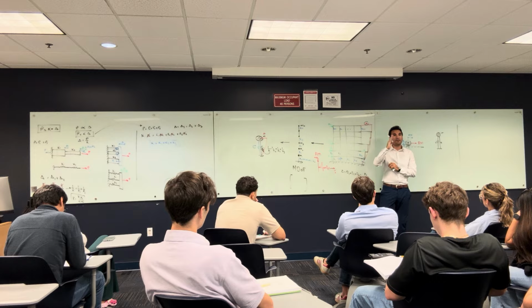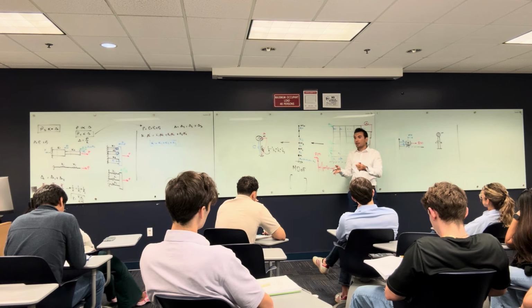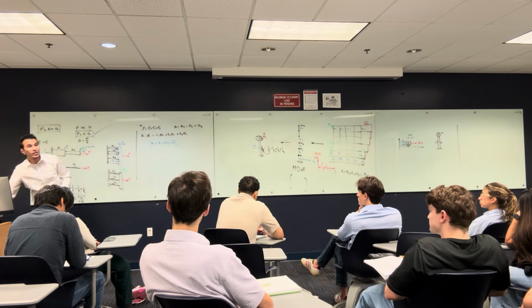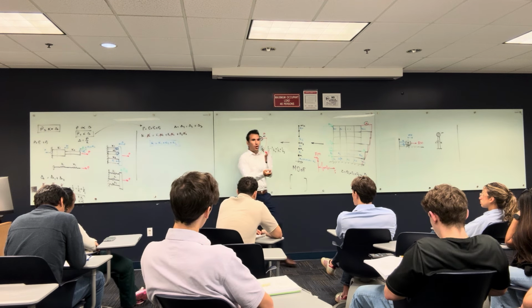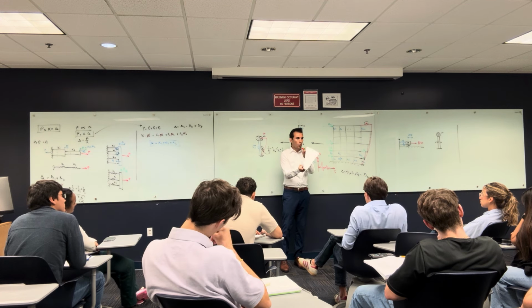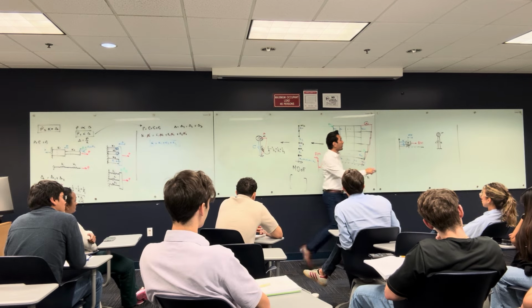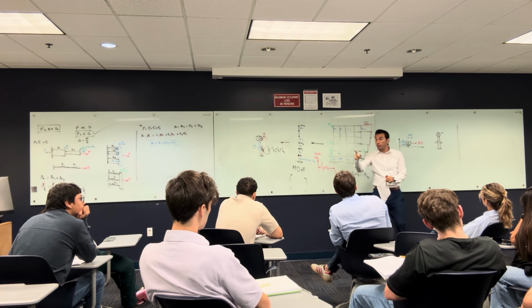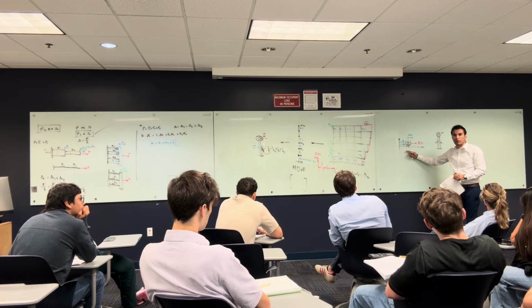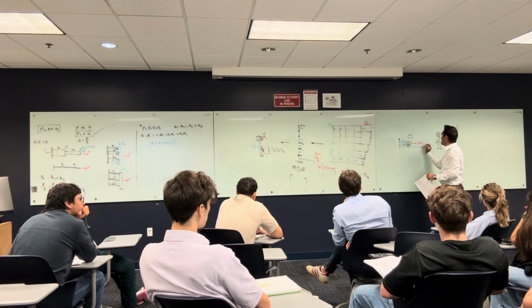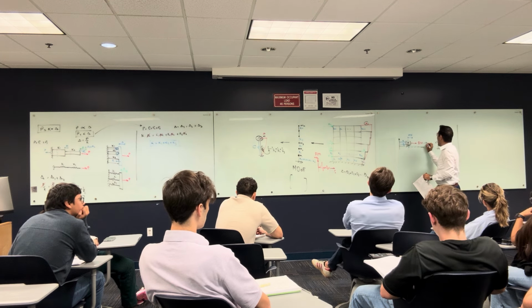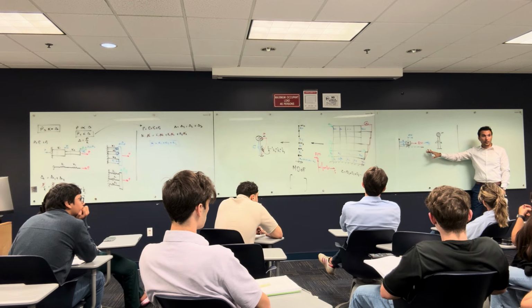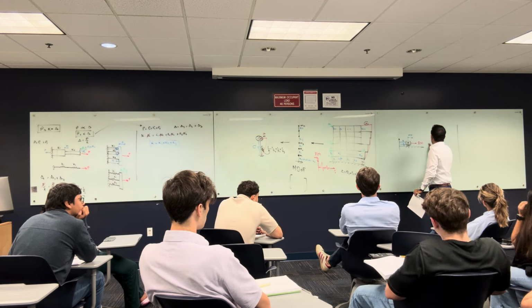However, every building is going to have a different response. Why? Because some buildings are tall, some are short, some are big, some are small. If you have a small building, it's barely going to move, right? If you have a tall building, it's going to have lots of acceleration. So this A is the acceleration of the structure, which is different from one structure to another. It depends on the mass, the stiffness, the damping of the structure. However, Ft is equal to, let's say, the mass multiplied by Ag, the Ag of the earthquake. All right? But let's take it out from here.